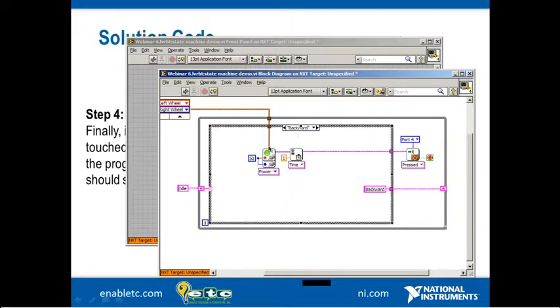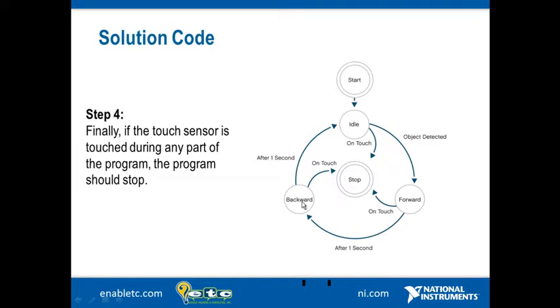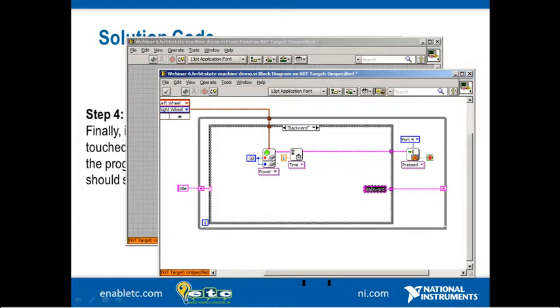And now we can tweak this code to do what we want. So instead of moving a value of positive 50, we want it to go the other direction, so we change the value to negative 50. The backward state, again, after 1 second will transition, but this time, instead of transitioning into the backward state as the forward did, backward state is going to transition into idle. So we just have to change this constant now to be idle.